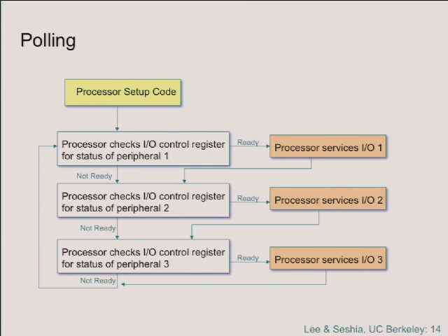Okay? So your interrupt service routine now has to be at that address. So whatever you want to do with that external hardware, you put at that address in program memory, and that's what will respond to the interrupt. So we'll talk a little bit more about that on Tuesday, and then move on.